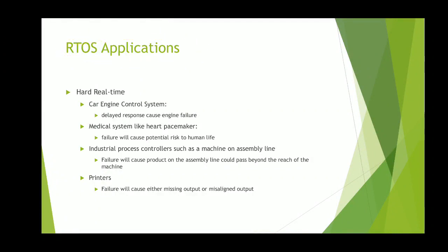Depending on the application type, we can select either a hard real-time operating system or a soft real-time operating system. For a time critical application, we normally prefer a hard real-time operating system, because a hard real-time operating system gives the output or response within the deadline. And these are the examples of hard real-time operating system applications.